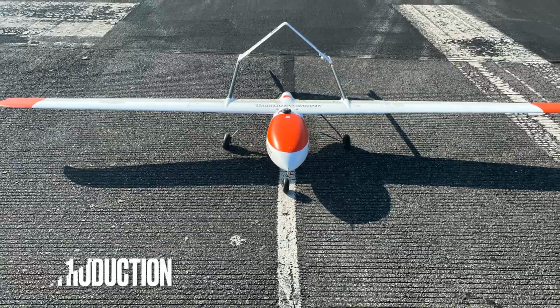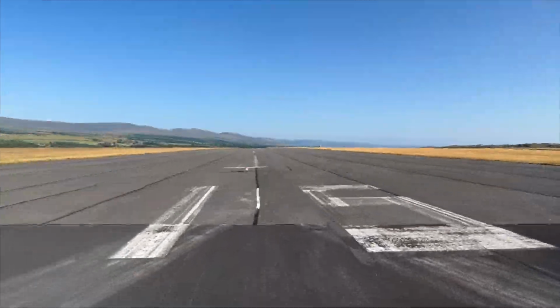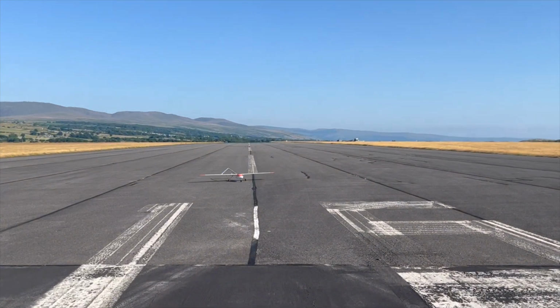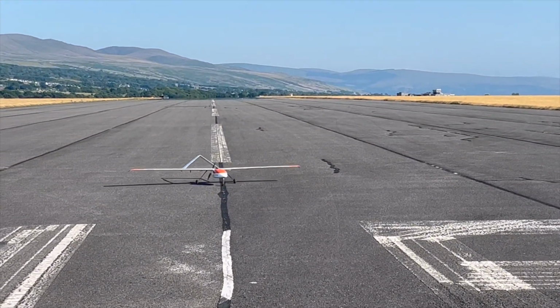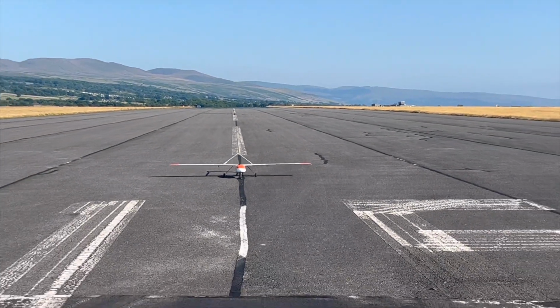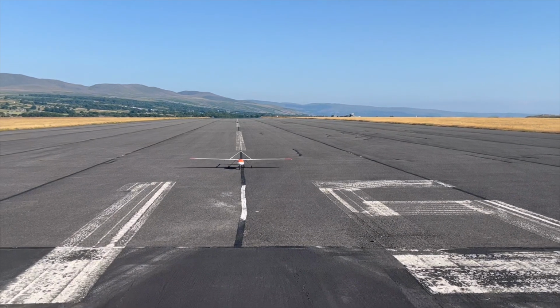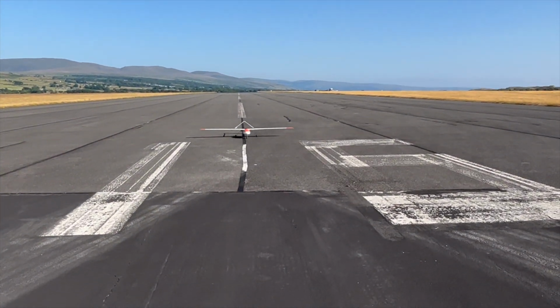Welcome to this briefing on the flight dynamics of the Albatros aircraft. This simulation-based project is designed to mimic the assessment and analysis that a test pilot would undertake before the first flight of this aircraft. We'll begin by verifying the aircraft's weight and center of mass using wheel reaction measurements to ensure proper balance. Thrust will be calibrated to gauge the static thrust of the engine based on RPM.